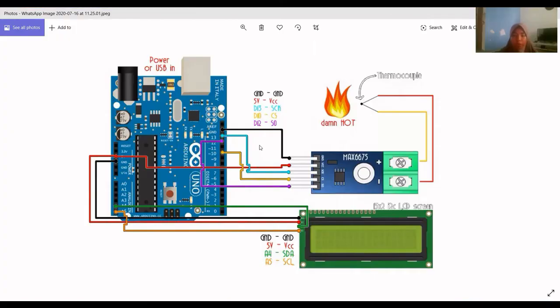Thank you very much. Then I'm going to explain the electrical part. First we are using Arduino Uno. We are using three Arduino Uno because we want to measure the water temperature, the inside egg temperature and the outer egg temperature. So we are using three Arduino Uno, three thermocouples, three sensors and three LEDs to show each of the measured temperatures. Here is the design of the circuit.